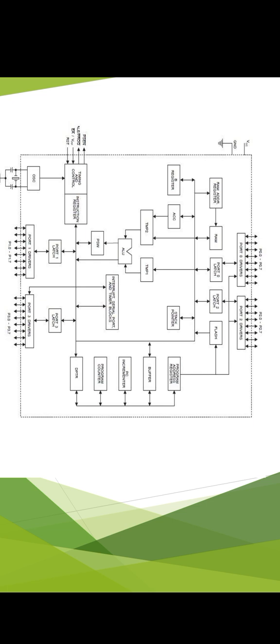Port 1 is also an 8-bit port, acting as a data bus for I/O in single chip mode, and a few device operations related bits in certain 8051 family variants in expanded mode. Port 3 acts as a data bus for I/O in single chip mode, and carries serial interface bits, timers T0 and T1, interrupt INT0 and INT1 inputs, and RD and WR for memory read and write in the expanded mode.